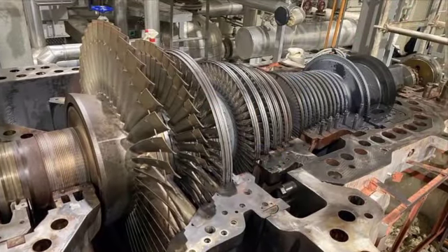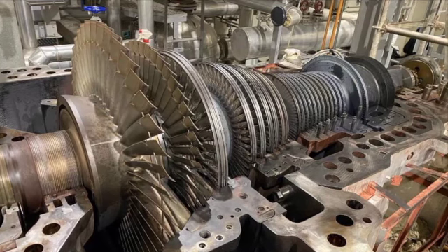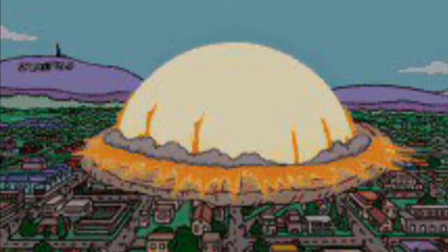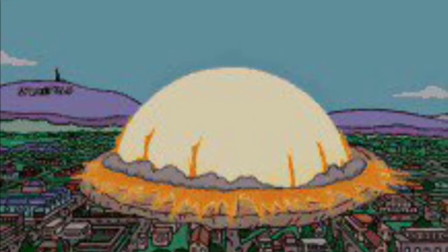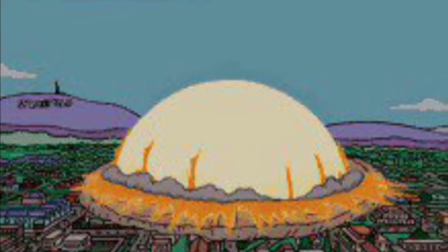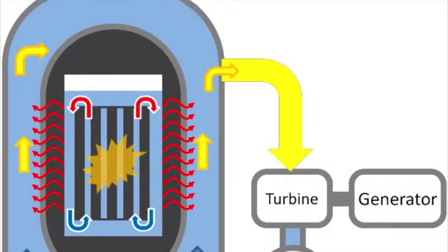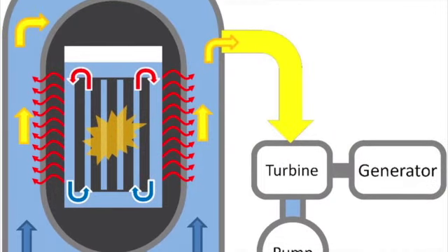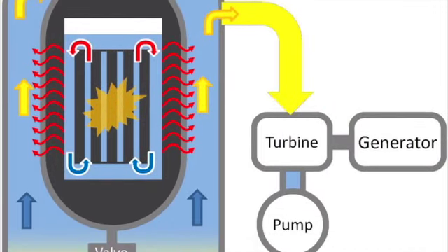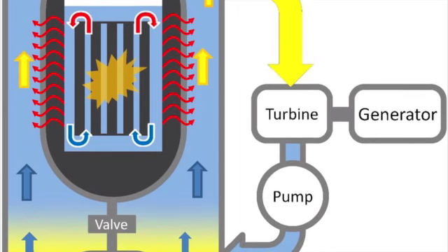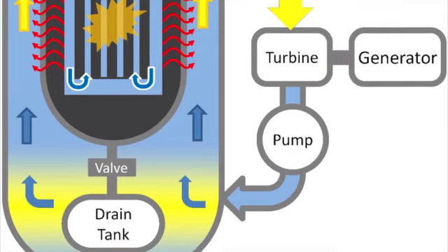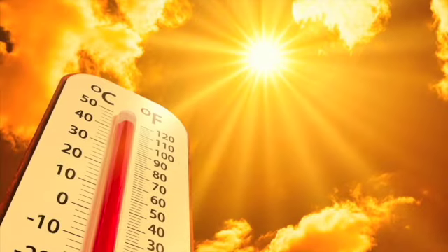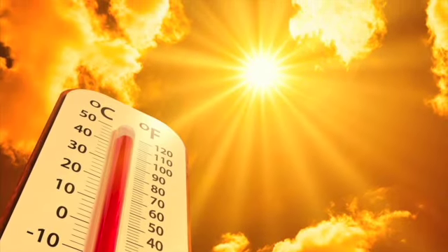Thorium reactors come with a number of key advantages over LWRs. Perhaps most importantly, they are significantly safer. A thorium MSR cannot melt down and operates at lower pressures than an LWR, reducing the risk of a pressure-related failure. Because a liquid fuel is used, it can be easily drained into tanks below the reactor in case of emergency. Additionally, thorium MSRs produce less waste than LWRs, and the waste they produce is less hazardous. MSRs are also more efficient at energy production, since they operate at higher temperatures and efficiency scales with temperature.